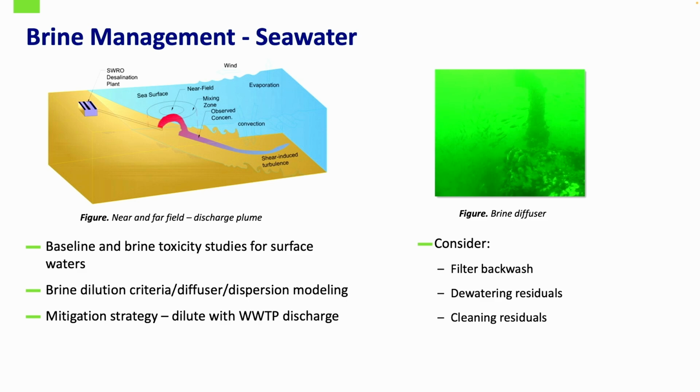And you want to consider, on the right there, filter backwash and all the residuals that are involved in the treatment process, because it's not just desalination. You'll have a lot of solids that you have to remove. They may have a DAF process. You may have ultrafiltration. You may have a conventional filtration prior to the RO process. And you have to deal with all those solids.